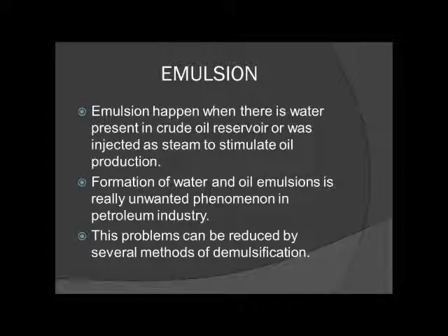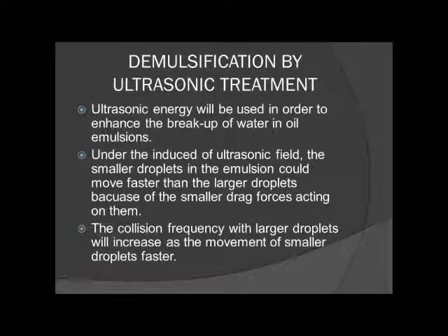One of the processes is demulsification by ultrasonic treatment. Ultrasonic energy is used to enhance the breakup of water-in-oil emulsion. Under the influence of an ultrasonic field, the smaller droplets in the emulsion can move faster than the larger droplets because of the smaller drag forces acting on them. The collision frequency with larger droplets will increase as the smaller droplets move faster.